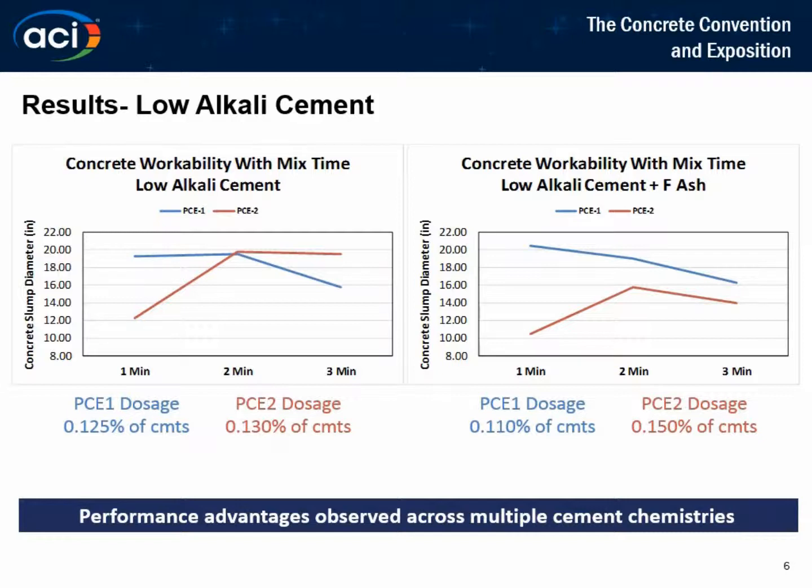And again, across both types of mix designs and across those changes in cement dictated by the alkali contents, you can make the leap, it's not such a huge leap to make, to say that not only do you see consistent faster dispersion with lower dosage, but you see magnitude less change in your dosage required across the two cements. So faster dispersion and less sensitivity to changes in cement.